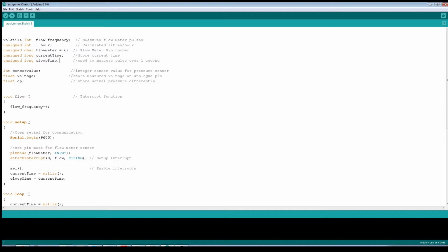In our case we've got a 1 second time period. We count how many times we get a pulse over that period, and then we can multiply that number by some scaling factors to determine our flow rate. This is usually called a pulse width modulated signal, or PWM, and those two represent two very common types of signals that you'll encounter.